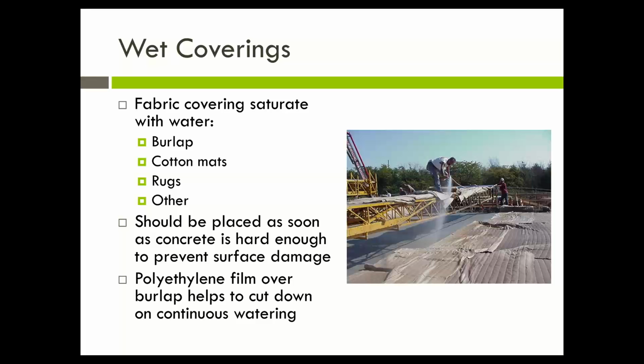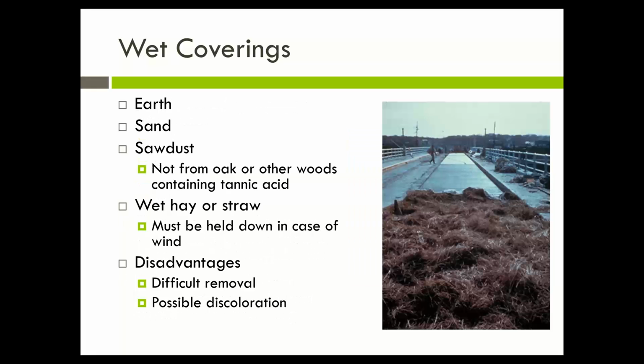You cannot begin curing too early from the point of view of maintaining water, but you can from the point of view of the surface appearance. If you put cloth on the concrete surface while the concrete surface is still soft, you run into a big problem. That big problem is that you will leave impressions of the cloth on the surface. You can put a polyethylene film down on top of the burlap to prevent evaporation, but if that has folds in it, you may discolor the concrete. And where the fold is, there's more oxygen, so you'll get a whiter color, and where the material is hard down and there's not very much oxygen, it will be darker, and that coloring will stay forever.